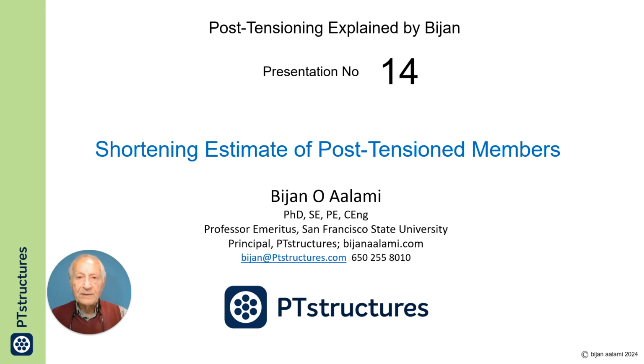All concrete members shorten, shrinkage being the largest component. The shortening does not have a significant impact on the performance of conventionally reinforced concrete, but it does on the performance of post-tensioned members if it is not recognized in design and not allowed for.